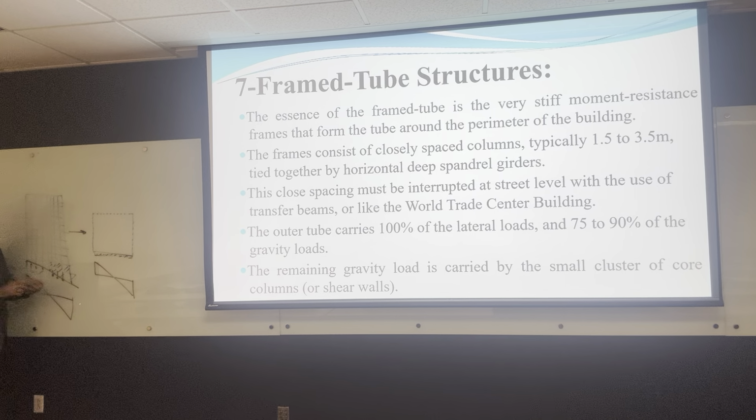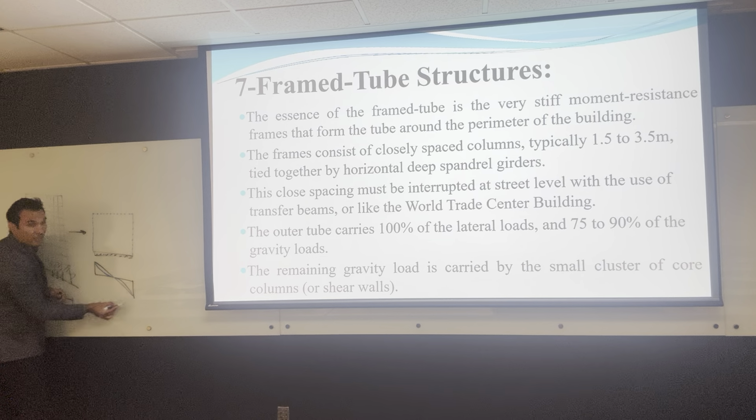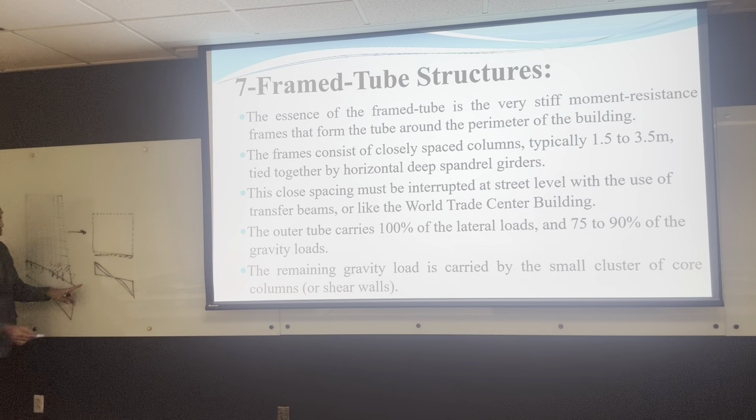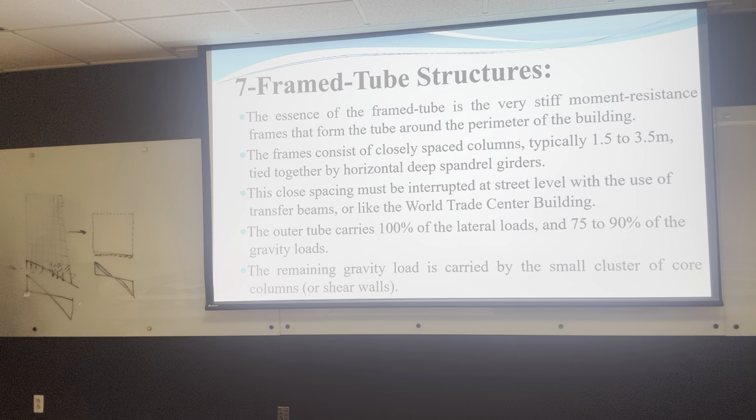Something is gonna happen, which is the strains are gonna be something like this. So if it's a shear wall, it acts with very good efficiency. But if it's a perforated shear wall or columns connected with beams, you lose all this resistance. And why has this happened? Imagine this as these beams. Actually what happened is the beam that is here is connecting all these columns together, right?